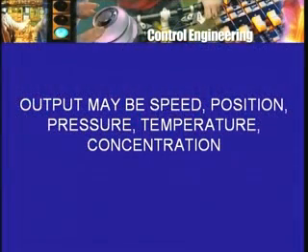In most situations, the actual quantity, of course, is actual. It's actually the motor running somewhere, or some bath having a certain temperature, or there being a certain pressure developed under a certain set of bellows or whatever. So the actual quantity is, of course, physical. It is speed, temperature, pressure, whatever. The desired quantity is in your designer's mind or on a piece of paper written as 1500 rpm.